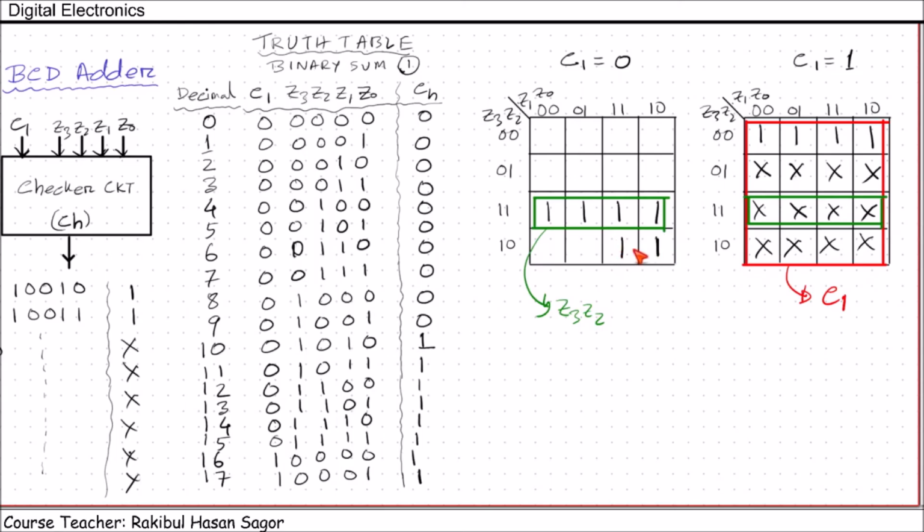Let us deal with the remaining 2. We can take 4 boxes. Once we have finished taking these 4 boxes, now let's consider they are on the top of this second Karnaugh map. Can we say that we have an adjacent cell in the top and bottom box? Yes, we have don't care conditions at the same positions of this blue box. So we can say from top to bottom, these 2 boxes are one single box.